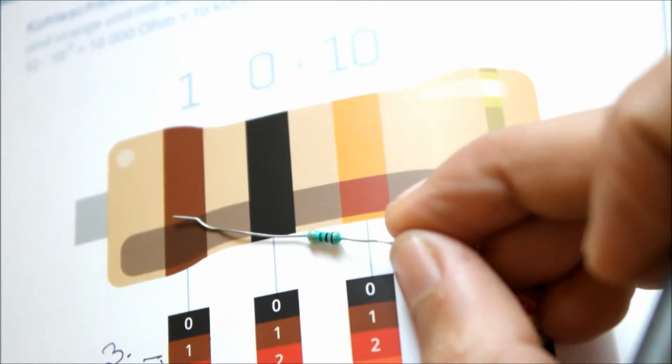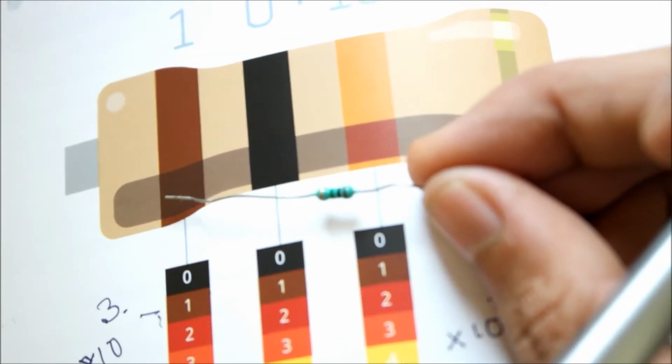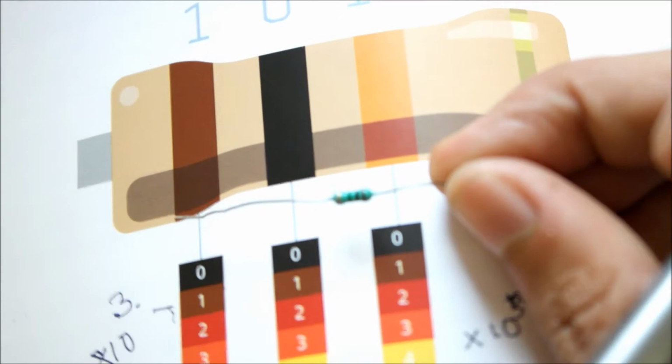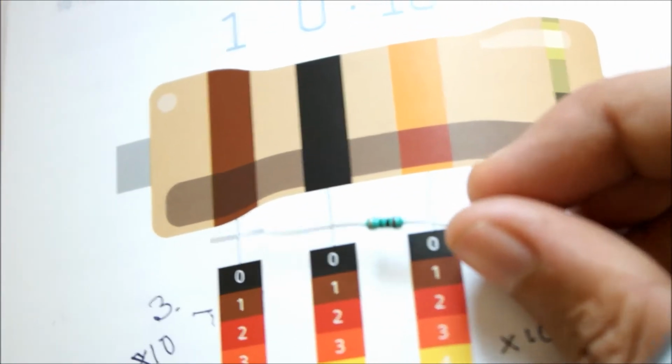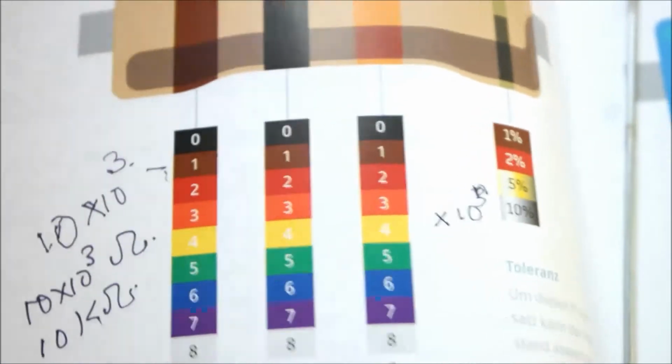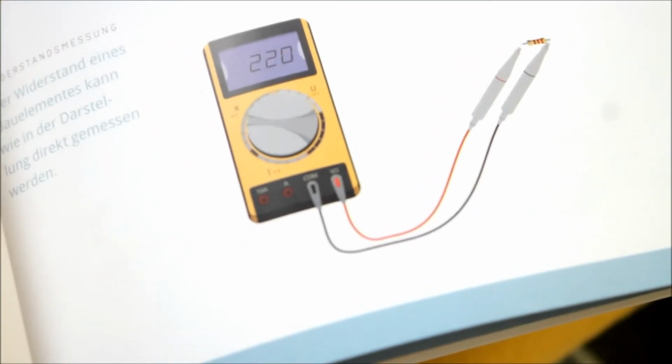Also, one very important thing about resistors, you can find out from their sizes. If they are as small as this one, these are called quarter watt resistors. If they are a bit bigger than this, then they are called half watt resistors. Also, if you don't like calculating your own resistor values by looking at the color bands, which I find sometimes time wasting, but it's a very good practice and a very handy solution if you don't have a multimeter with you.